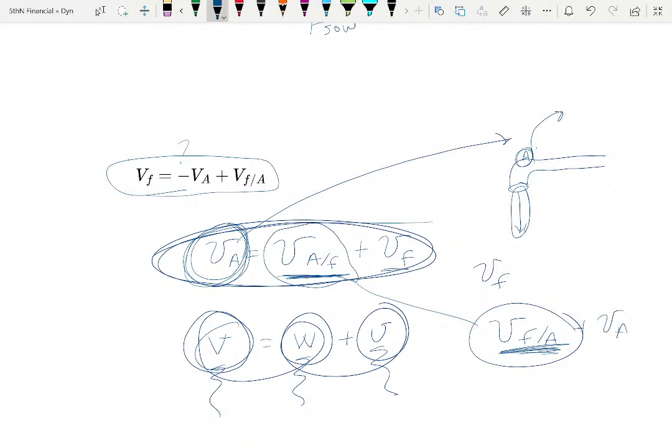If you think about it, the fluid's still got to come out of the pipe, right? So when it's coming out of the pipe, you're seeing M dot is equal to rho times the area of the end of that pipe times the velocity of the fluid relative to A, because that's what's coming out of that pipe. So if this thing is spinning, all of a sudden, as it's spinning, the velocity of the fluid starts changing because it's spinning.